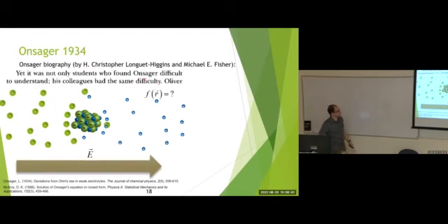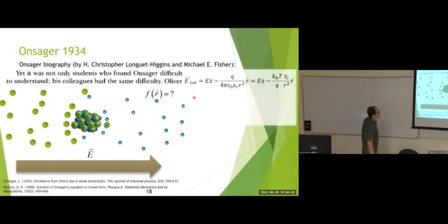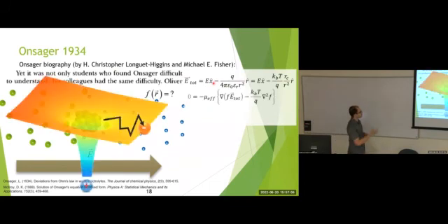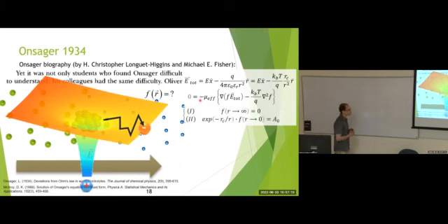And the variable here is this F, which is the distribution of bonded ion pairs. And the electric field he used was the external electric field, as in here, plus the electric field of Coulomb interaction. And this is the shape of the electric potential used. Use the drift diffusion term and the continuous equation equal to 0 because we are in steady state, and these two boundary conditions.